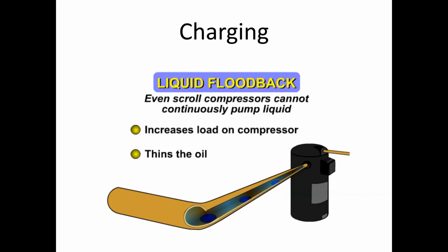The way that that suction line runs now is that it dumps that suction gas directly into the scroll set. So these compressors are a lot more susceptible to being damaged by liquid than earlier designs were. Why did they change the design? To make them more efficient, right?